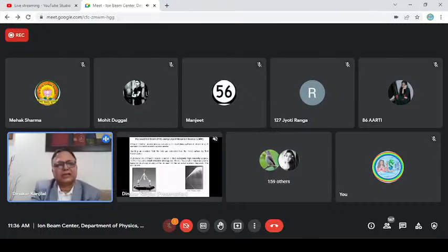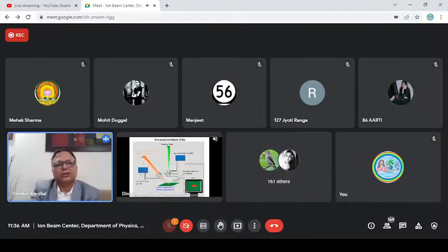And here at the ion source itself, this becomes a micrometer, a fraction of a micrometer. So when it goes to the column, this is the focused ion beam column. I will show the actual column later. So it gets focused to a few nanometers here. That is the beauty of that. And with this SEM, one can see also by electron spectrometer. And then this detector is a kind of secondary ion mass spectrometer. One can see the ions which are scattered out.